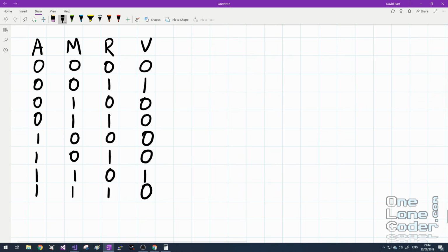And what we see is the overflow bit is only set for two situations. So I want to derive a logic formula that gives me these results. Well, to begin with, I can see that the ones are set if the value in the accumulator is not the same polarity as the value in the result. I can represent that as the exclusive OR between the accumulator value and the result, which gives me 0, 1, 0, 1, 1, 0, 1, 0.